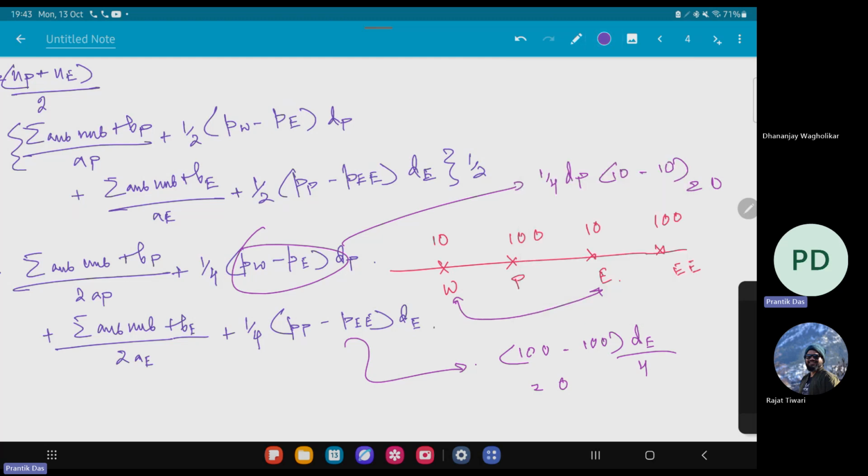One of the modifications that we did earlier was algorithmic, that is called the SIMPLE algorithm. Another way of doing it is basically Rhie and Chow interpolation. While discretizing this EV as a function of this EV plus EP divided by 2, we are going to introduce some correction terms so that this discretization becomes sensitive to the checkerboard arrangement of the pressure itself, which is taken into account while getting the equation for the velocity after discretization of the Navier-Stokes equation.